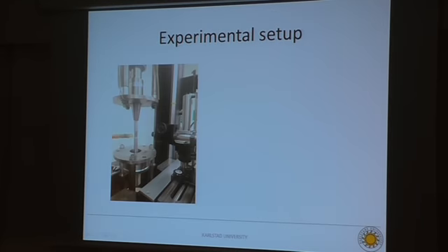Here are the experimental setups, just so we can see how our setup looks. We can see the ultrasonic fatigue testing machine with the horn and oscillator up here. Here we have our specimen, and here we have a camera pointing at this plane surface in the middle, where the camera is connected to computer software where we can measure the crack length. And we are also using cooled air to cool the specimen while testing.